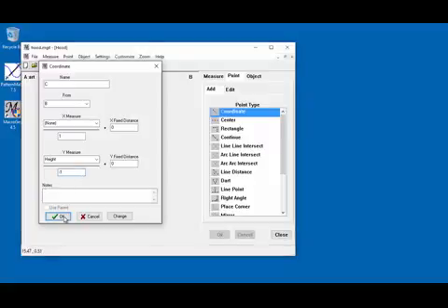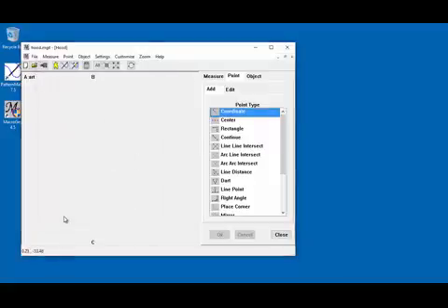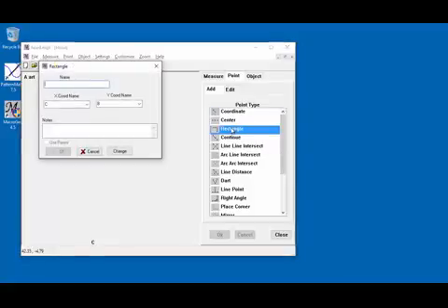OK. Click OK. Notice that we're just creating points here. We haven't connected the dots. We'll do that later. Now let's add point D to complete the rectangle. To create it, we're going to use a rectangle point instead of a coordinate. So that's point, add, and then rectangle. The rectangle point type means that no matter where points A and C are placed, D will automatically be put at the corner of the rectangle. I'll show you and you'll see what I mean.